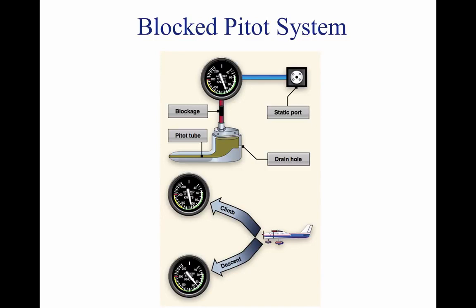as seen above. The pitot tube may become blocked during flight due to visible moisture. Some aircraft may be equipped with pitot heat for flight in visible moisture. Consult the AFM/POH for specific procedures regarding the use of pitot heat.